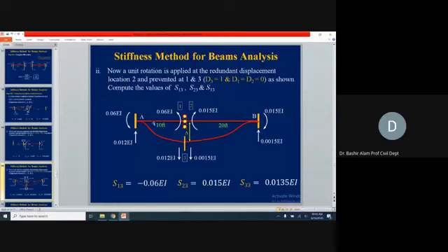Originally it is this top straight line, but it is coming to this one now. The left portion, if we select it, will try to come back to its position. So this is how we have found this counterclockwise direction. It will be 6 EI delta divided by L square.